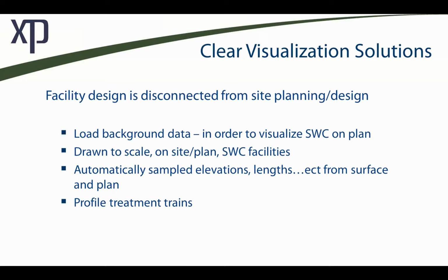So maybe there's runoff draining to a swale. Maybe there is a spreadsheet you're using, and you're going to look at, all right, the swale is 2 feet deep, 1 to 4 batters, it's 100 feet long. Based on that, you know the volume, in theory, of that facility. Okay, well, what if in the real world that swale is at a 2% slope? Well, you're not going to be able to store water in that whole facility because it's at a slope. So really only one side will pool up to the top. The other side isn't quite full, right?